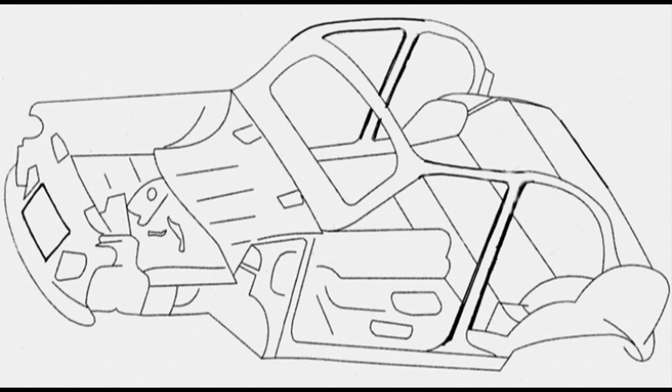So this body or the shell, you will find it has got a structure on which we can fix different components of the automobile, be it an engine, be it transmission system, be it steering system, axles, wheels and everything. Broadly, it is in the form of shape of automobile. Different components can be placed inside it. To improve the things, we have subframes. Now these subframes carry engine or transmission system, and these are fixed on the main unit.